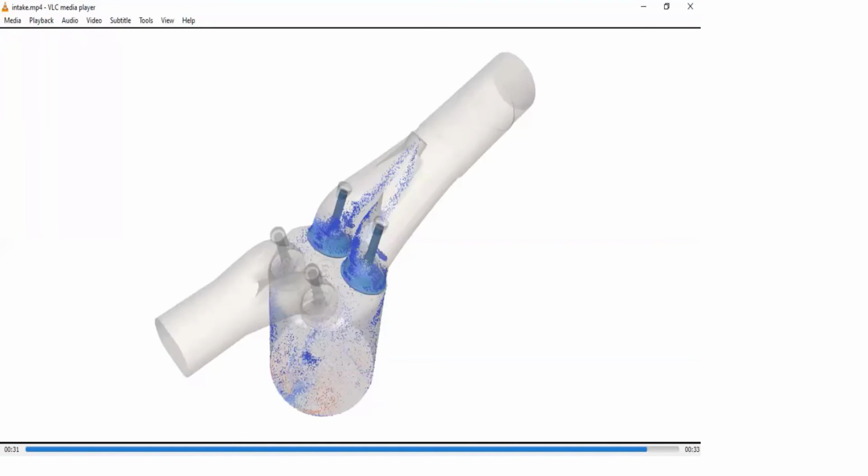Okay, and if that much air is there, you can determine how much fuel you can allow, because otherwise it will be a lean mixture or a rich mixture, correct? Yes, sir. So that should not happen. If it is a lean mixture, then a problem will come during the exhaust. If it's a rich mixture, again the problem will come. So NOx will be produced, then carbon monoxide and all these things will be produced.